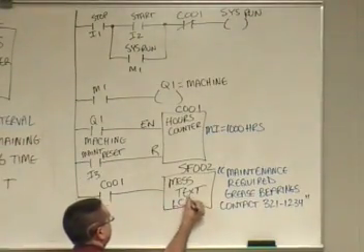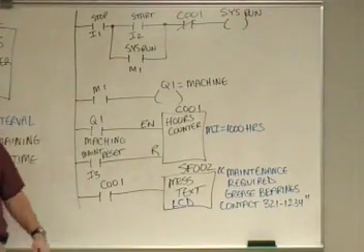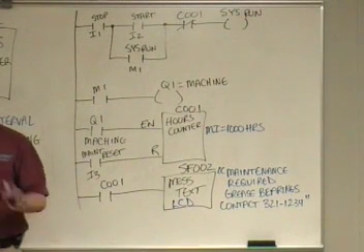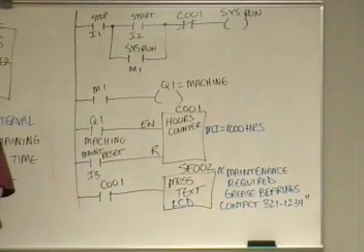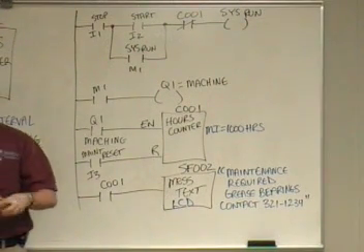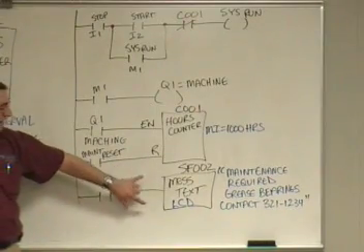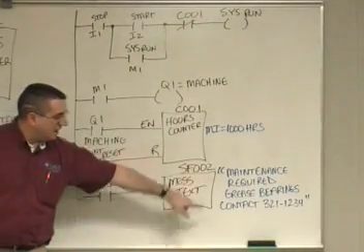On the LOGO! LCD, that message text, as soon as this machine has been running for 1,000 hours, it's going to shut down. Cumulative 1,000 hours. I could run it for 2, shut it down for 10, run it for 998, and now that equals 1,000, right? So as soon as it gets to a cumulative 1,000 hours, it's going to shut the machine down. It's going to say that on the screen.